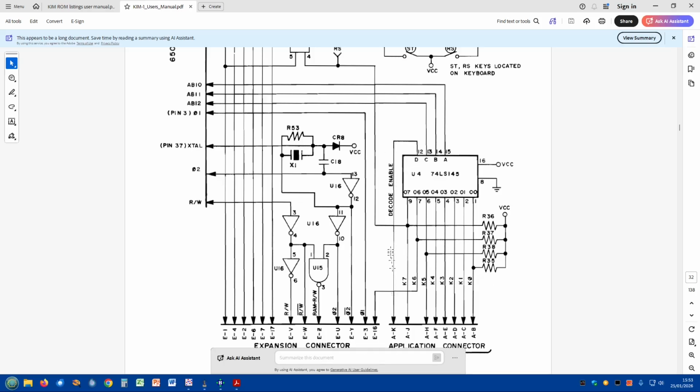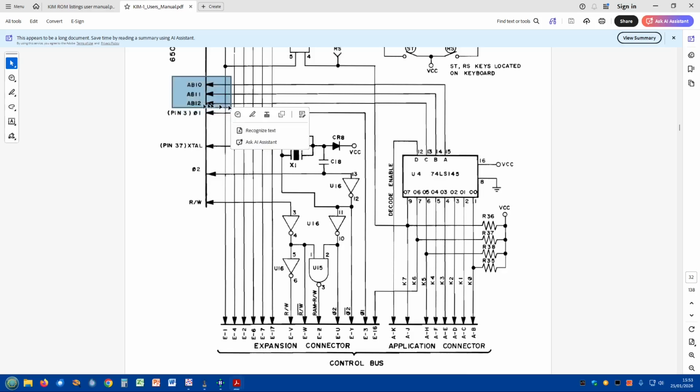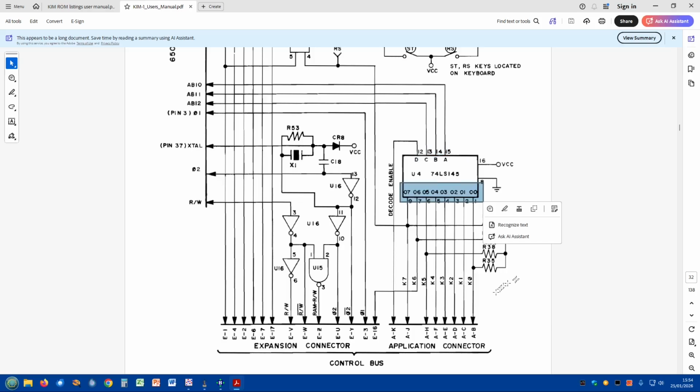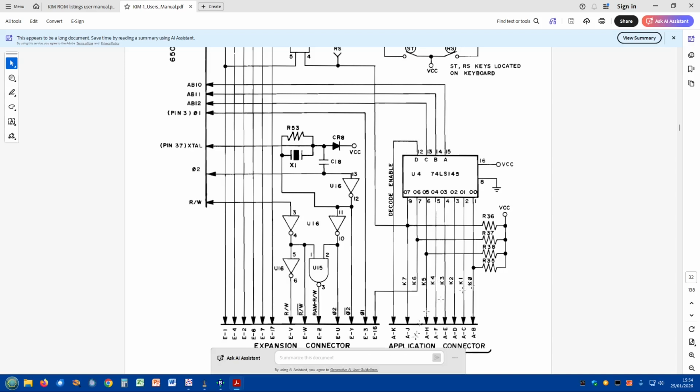This is that extra wire link that I showed you. When this is pulled down to 0, then address lines 10, 11 and 12 over here feed through to here, get decoded to give us our 7 different chip enables, well, I say chip enables. Each one of these is kilobyte 0, kilobyte 1, 2 in the memory address range. We'll look at the memory space shortly. Some of these are held up positive. So it's quite a clever way of enabling and disabling all this addressing just through this one bit here. So you can use this to add extra decoding to the address range to allow more memory to be added elsewhere.